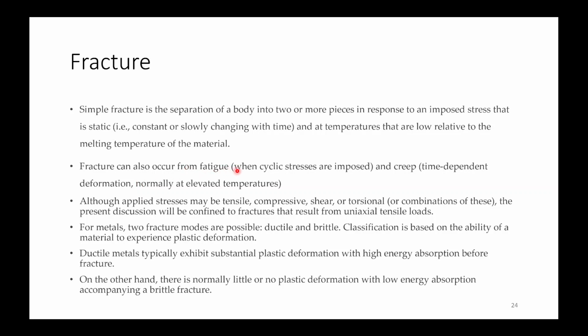Fracture can also occur from fatigue and creep. So in case of fatigue, what will happen? There will be cyclic type of stresses. This we will be studying in the next chapter. And creep will be when there is time dependent deformation at elevated temperatures. Now although applied stresses may be tensile, compressive, shear or torsional, or a combination of these, the present discussion will be confined to fractures that result from uniaxial tensile loading.